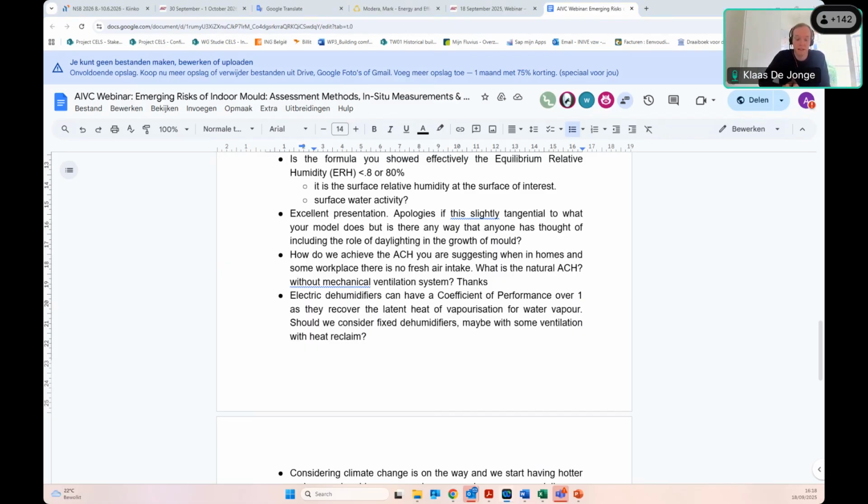But of course, the first step if you want to increase energy efficiency is to tighten, to add rubbers or maybe change the window if it's allowed, and actually decrease the infiltration rates. And at that point, dedicated mechanical ventilation systems, ideally a bit controlled for energy efficiency reasons again, seem to be the way to go. If that's not in place, then if it's not an option to install such things, you do need to air tighten everything.